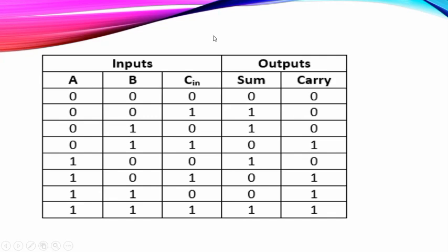I will be showing you how to add it. So 0 is the first input, 0 is the second input. So 0 plus 0 is 0. Okay, so when you add these both, 0 plus 0, you'll be getting output as 0. And when you add the output of the first 2 inputs to the Cin, that is 0 plus 1, you will be getting 1 as the sum and 0 as the carry. Okay. So similarly, we'll be doing the additions of all other steps.